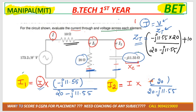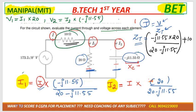Voltage across each element means we need to calculate V1. V1 is equal to I1 into 20. We need to calculate V2. V2 is equal to I2 into minus j 11.55. And we need to calculate this voltage. So how much will this voltage be? Let us consider V3. So V3 would be equal to I into 10.